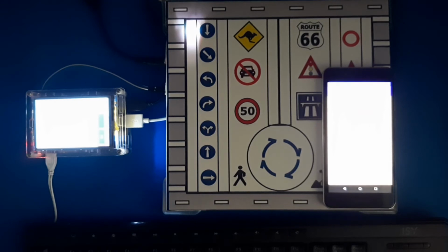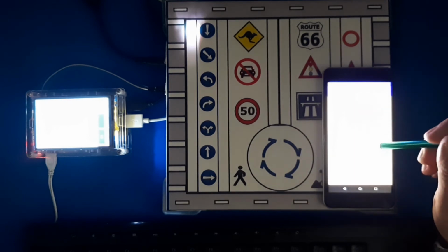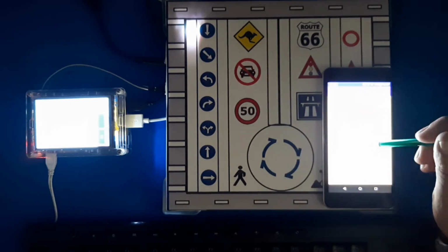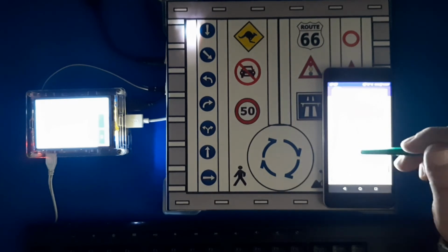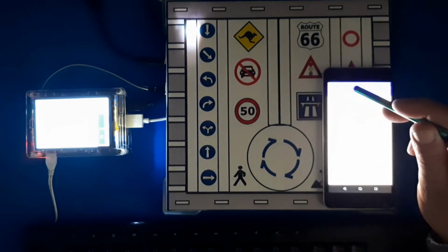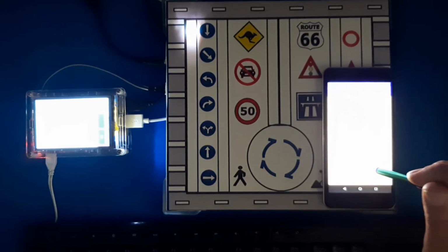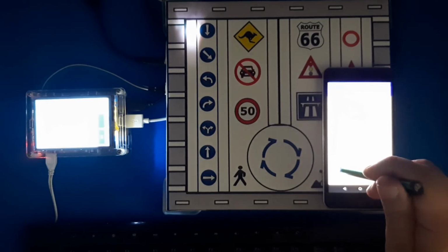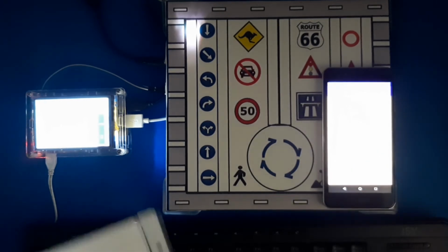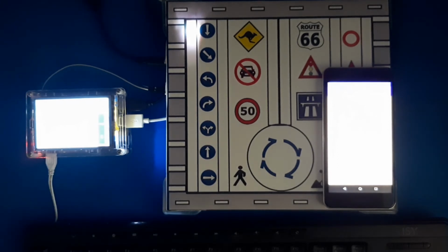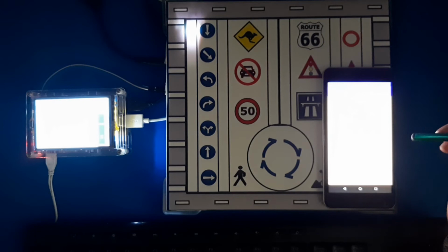We will go through 2 demonstrations. One is a game demo and the second one is a mode demo. So let's start off with the game demo. You select game at the top. Select the country, for instance UK. Make sure the IP address of the Raspberry Pi is correct. And then you press Init. The UK shows up on the Raspberry Pi. And we can start the game.